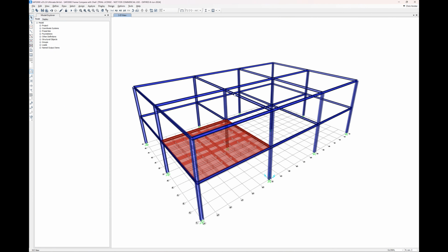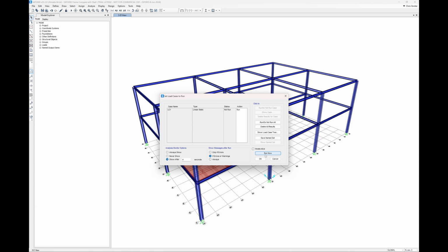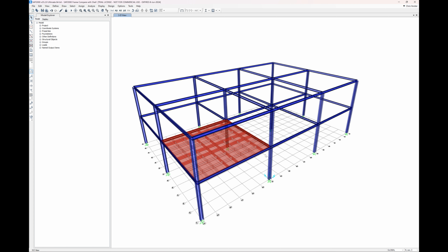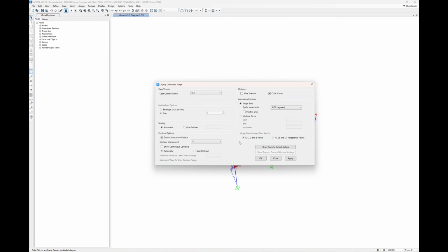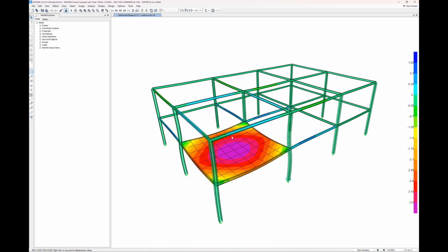And we can do that for all the sections, but we won't do it for the sake of time. But we've already run those comparisons and they're verifiable. So if we run the model, we can see the load case. We only had one in GenFEA, but if we had multiple, they would appear here. All the load cases and load combinations will be brought across. And once we run the analysis in SAP 2000, we can start looking at results and comparing that with GenFEA. So we're switching on the deflection in Z.